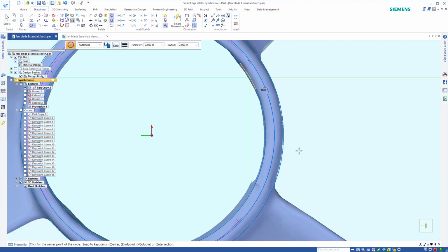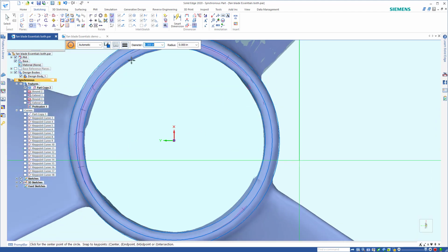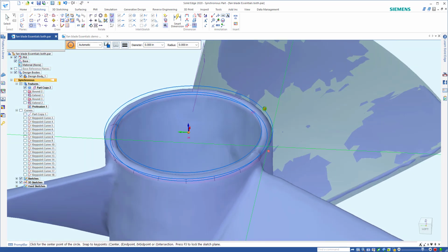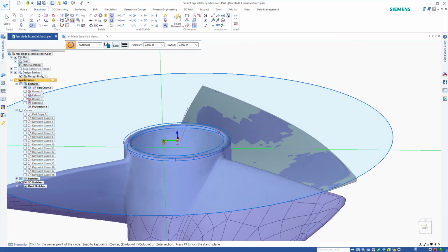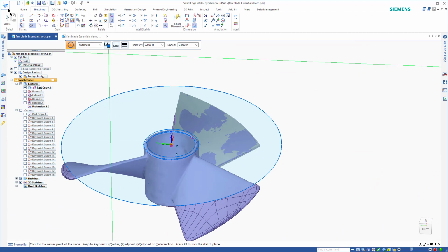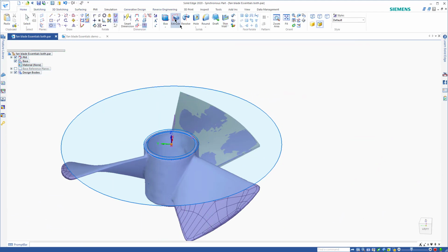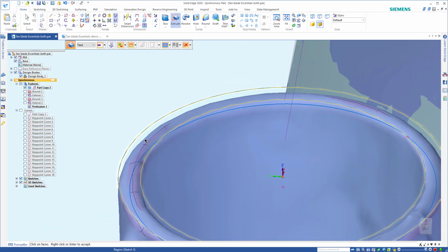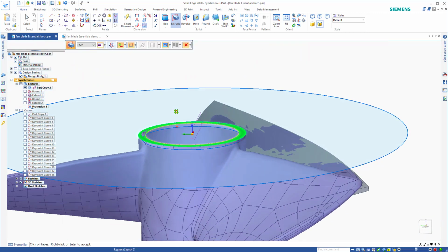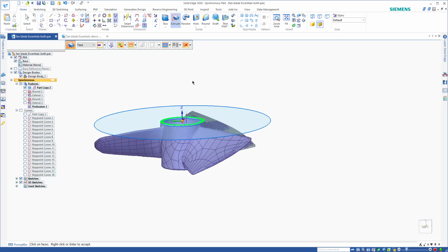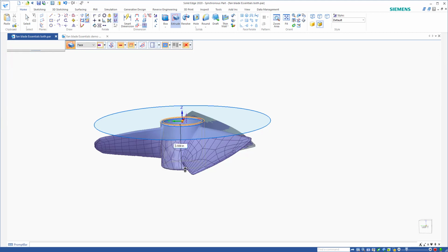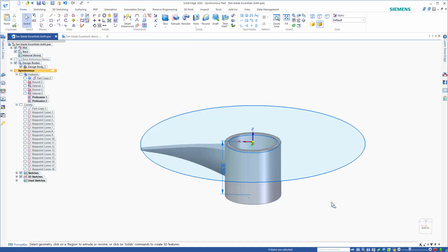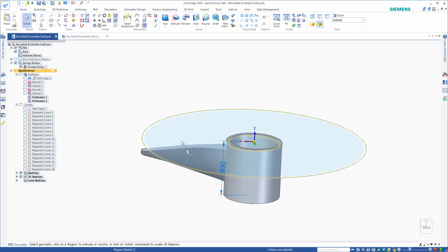So if I'll just create that, the outer and inner. And again, you can dimension it as you see fit. But you see that I just drew the two shapes. But you can redimension it like I just did earlier, and then come back over to extrude, grab this area here, and then extrude that. Let's do that 0.93. So there we have our shape.